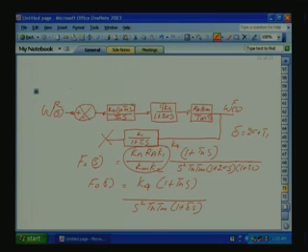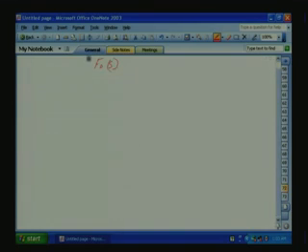So let us draw the Bode plot of this one. Again the loop gain will be equal to K4 divided by S square Tn Tm into (1 plus delta S), and in the numerator we have 1 plus Tn s.